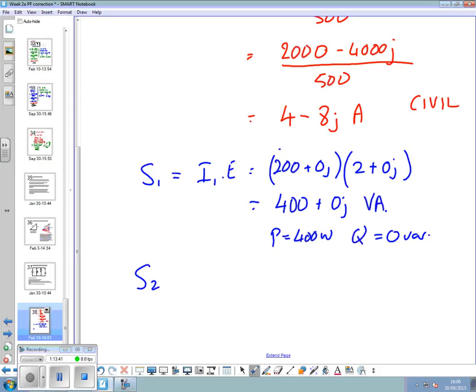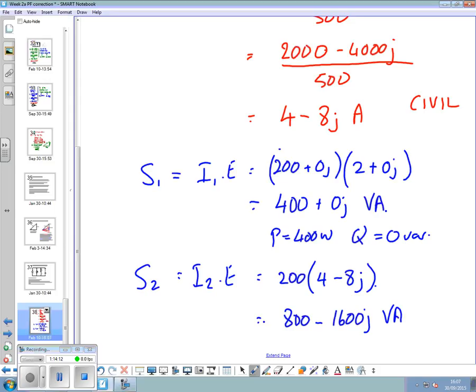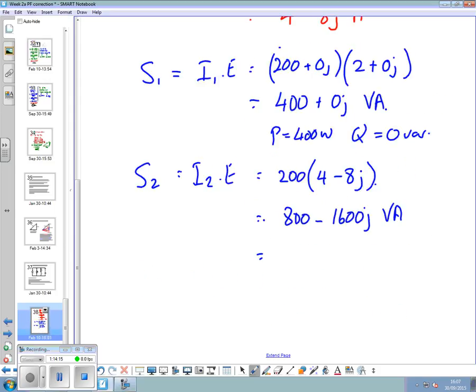S2 is I2 times E, that's 200 times 4 minus 8J, that's 800 minus 1600J VA, which is P is 800 watts, Q equals minus 1600 var.